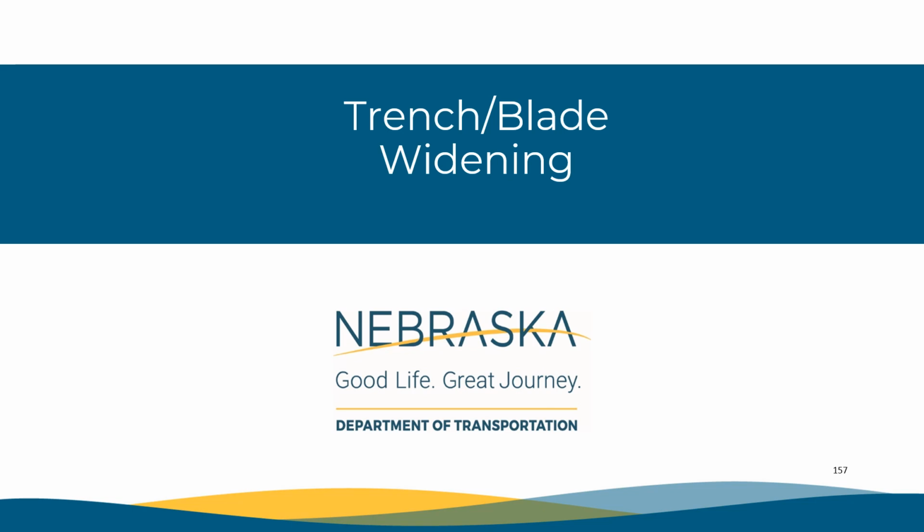Let's start with roadway widening. Trench and blade widening is typically used when a roadway is being widened anywhere from 1 to 4 feet. We will see it done by the use of motor grader and with a milling machine. Here is a series of videos on a project showing several different methods of this operation.